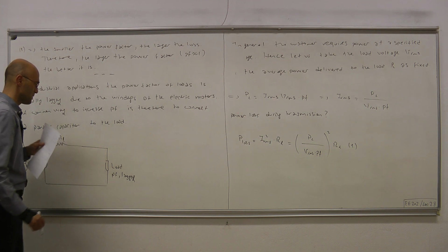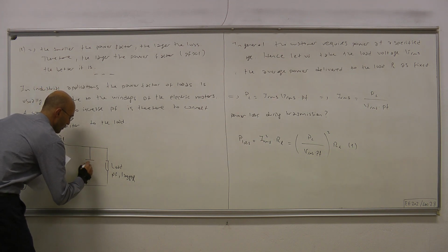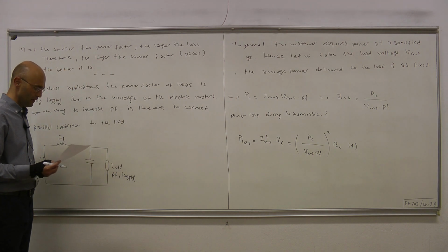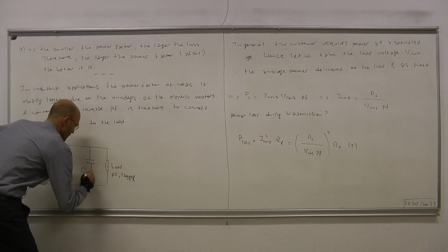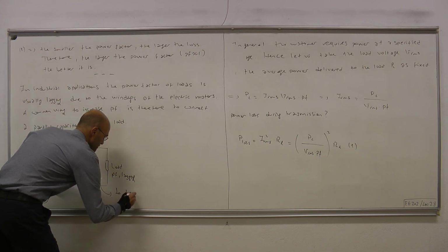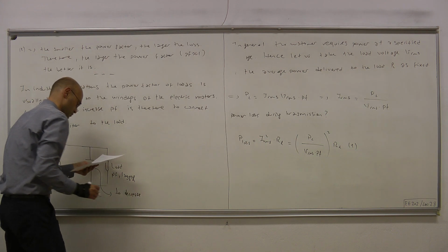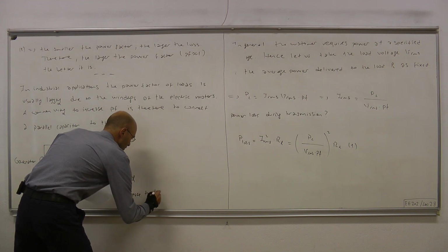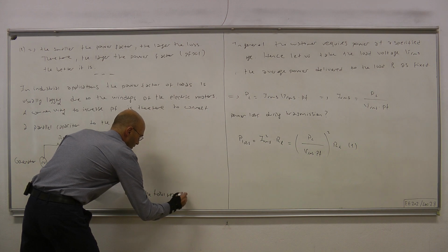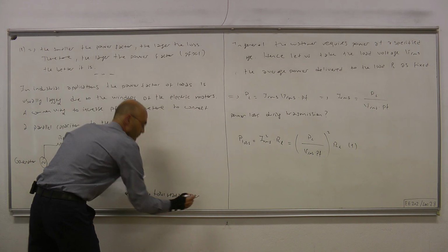So what we do is we connect to the load in parallel a capacitor, to decrease the total reactive power.